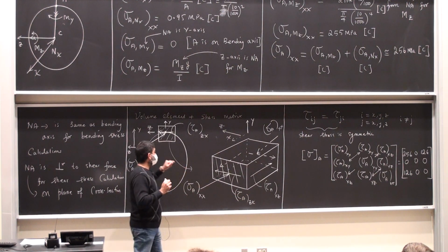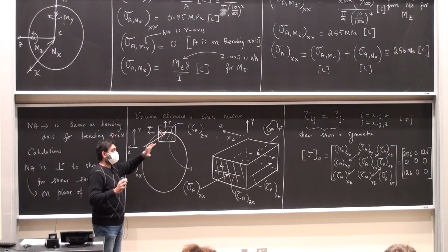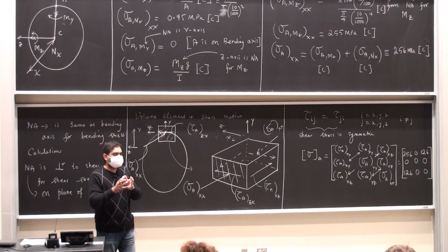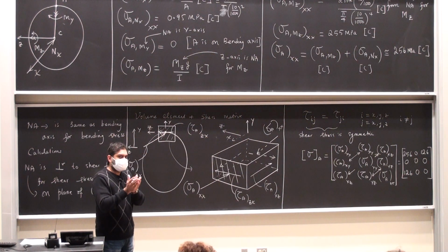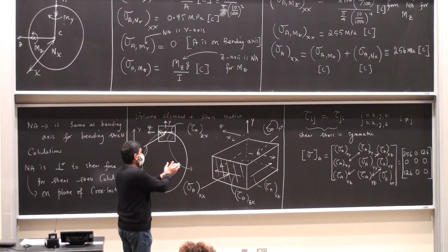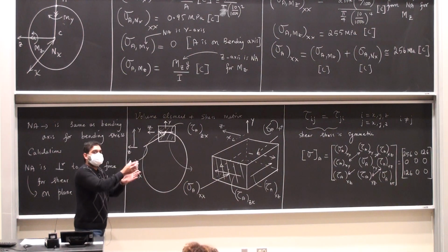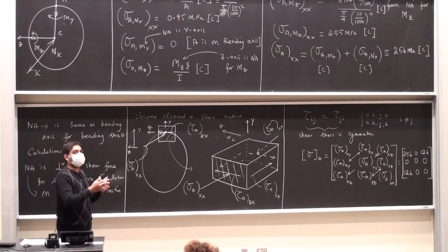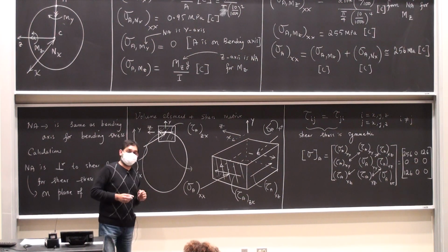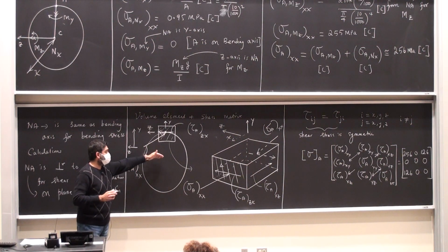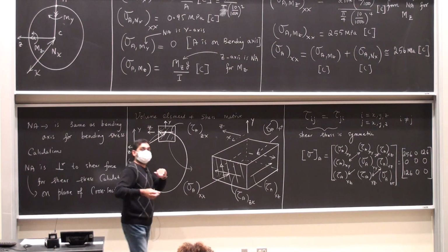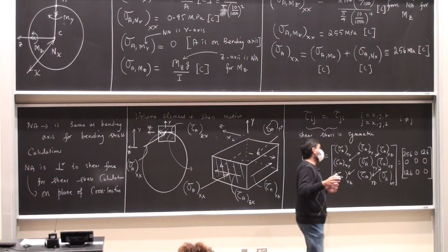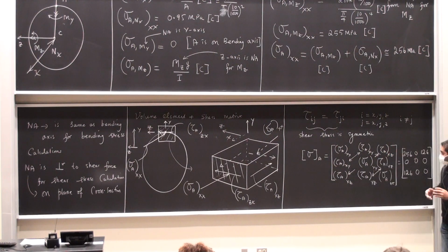And if you look at it, each point is actually a volume element in reality. We are drawing it as a volume element so that it's much more visible to us. But really, there are all these stresses that are sitting in a volume element at a point. And you've got to do this for each and every point. So for different points, these stresses will be different. We're not going to do this in this class, but you can find the eigenvalues of this matrix.